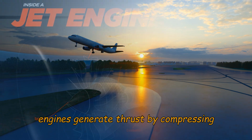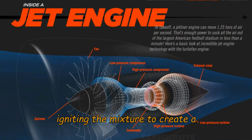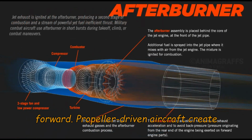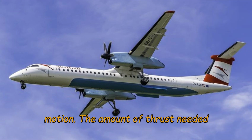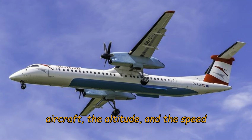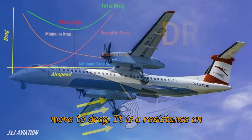Jet engines generate thrust by compressing incoming air, mixing it with fuel, and igniting the mixture to create a high-speed exhaust that pushes the plane forward. Propeller-driven aircraft create thrust by spinning their propellers to pull air backward, generating forward motion. The amount of thrust needed depends on the size and weight of the aircraft, the altitude, and the speed required for stable flight. Now let's move to drag.